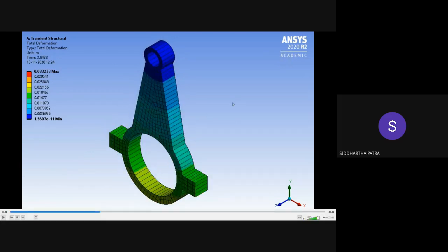Because of the shape of the connecting rod, the center of mass would be closer to the larger circular hole compared to the smaller circular hole. What I'm trying to say here is that once I get the time taken for 10 oscillations and divide it by 10 to get the time period of oscillation, the time periods in two different configurations are going to be different.